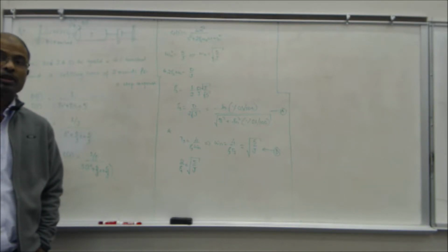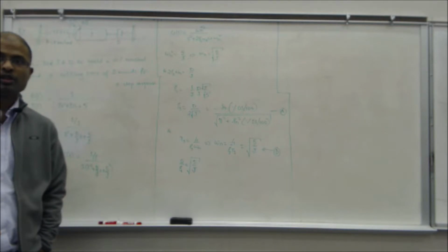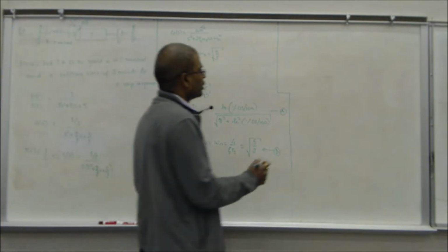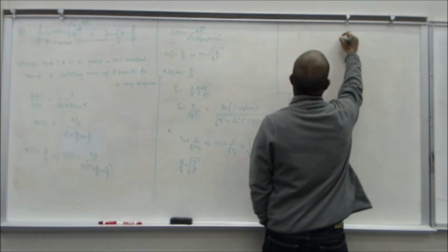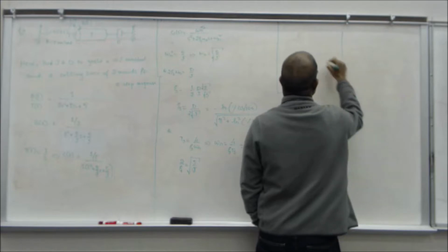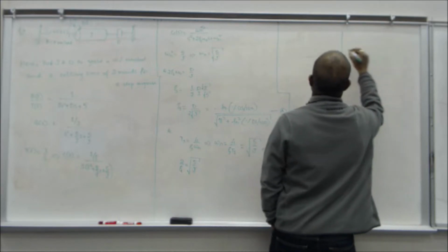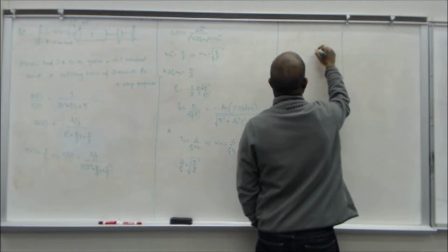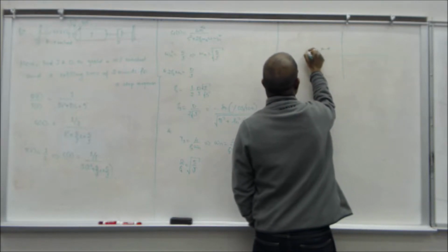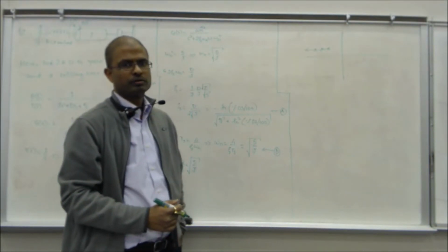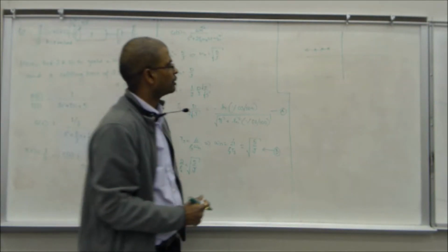You can keep the damping ratio the same, which means if you do a pole plot or a pole zero plot, if you increase the real part, the poles are going to increase in that direction. Okay?